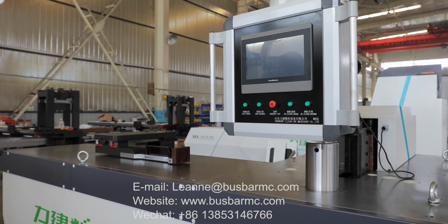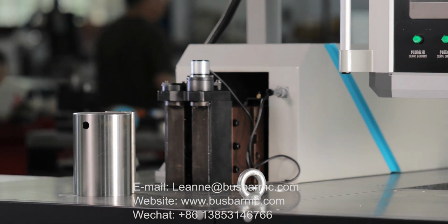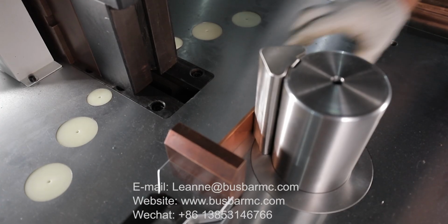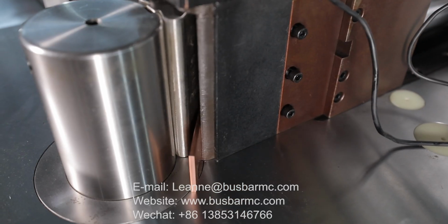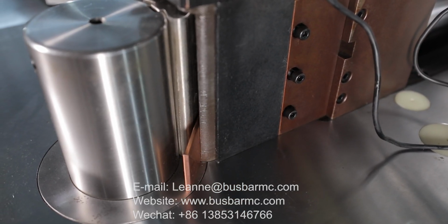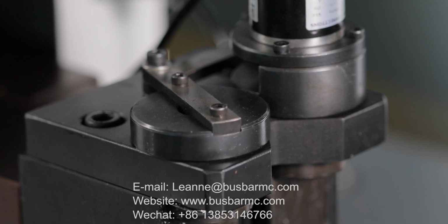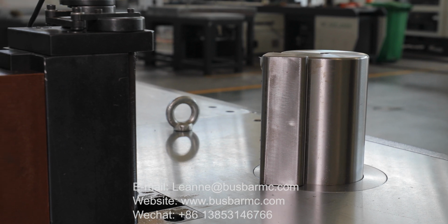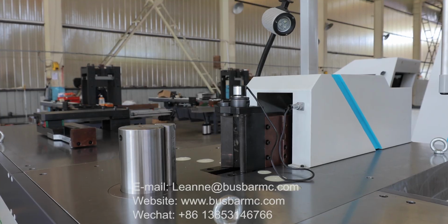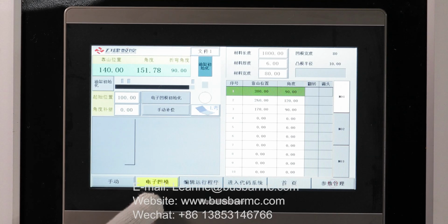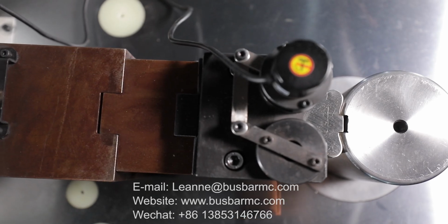The structure of the machine adopts an upper open type, which can conveniently take and place bus bars, and the bending power is supplied by double pumps to ensure bending efficiency and bending precision of the machine. The gauge of the machine is servo-controlled, and the position can be adjusted manually according to the needs, which can easily realize the control of the position of the bus bars during the work of flat bending and vertical bending. The machine also can be equipped with an electronic die system that detects bus bar bounce according to customer requirements.